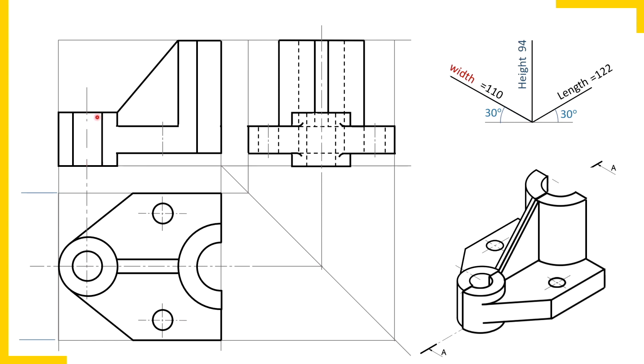So in this portion, this rectangle, what is this rectangle? Inner surface of the hole. We must not draw hatching lines here. This rectangle here, this is inner surface of semicircular slot. We must not draw hatching lines here.